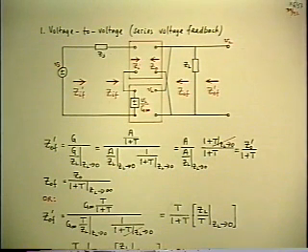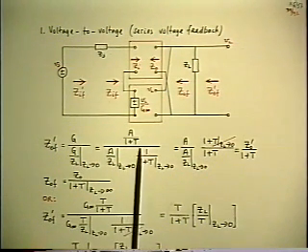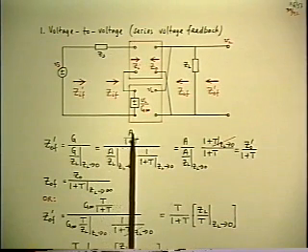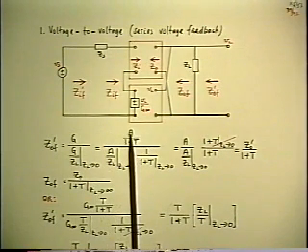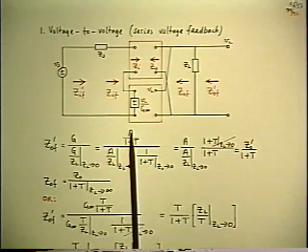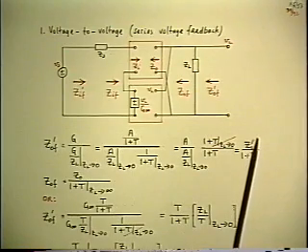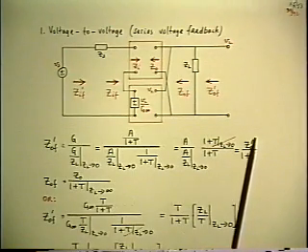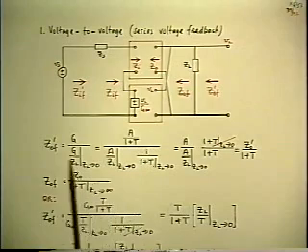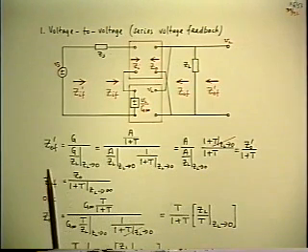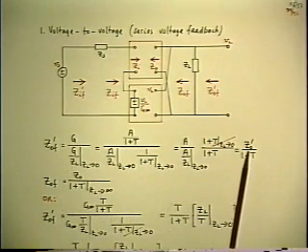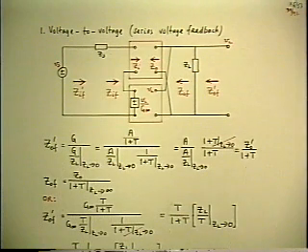So by exactly the same argument, which led us to abandon the A, because we don't care what the open loop gain is in the final result, by the same argument, we don't care what the open loop output impedances were either. So why not reformulate the result for the output impedances and avoid referring them back to the open loop values that we're not interested in?